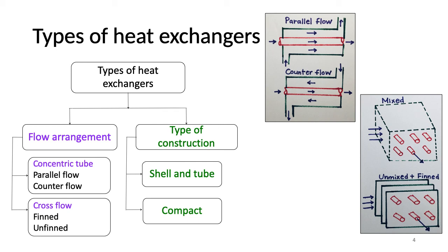In cross-flow heat exchangers, both finned and unfinned designs can be found. In the finned type, both fluids are unmixed, and in the unfinned type, tube flow is unmixed while the other fluid is mixed. This is shown in the second figure.